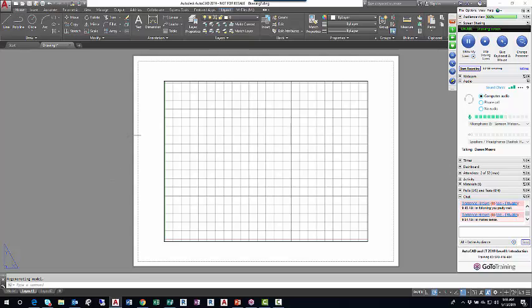They are environments that used to be called paper space. In fact, parts of the interface of AutoCAD still refer to the term paper space. We used that very frequently in the past with AutoCAD. Model space was where your drawing lived. Paper space is where your border lived, and you would print from paper space.